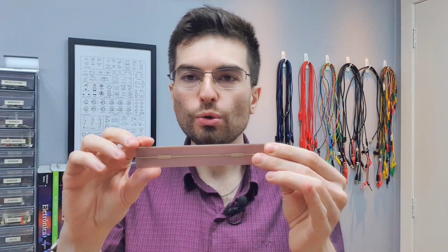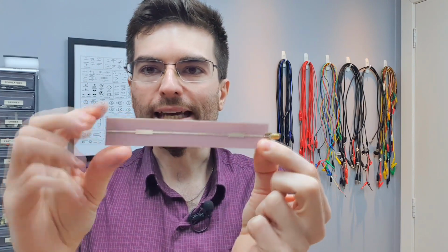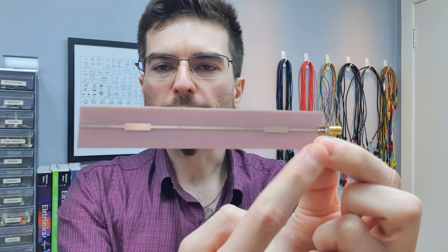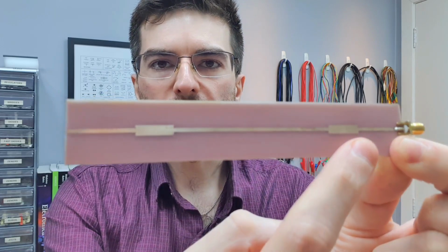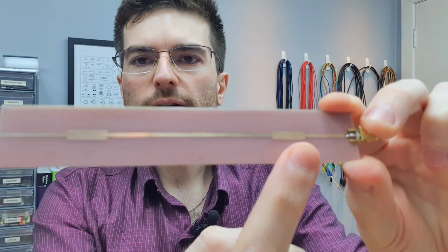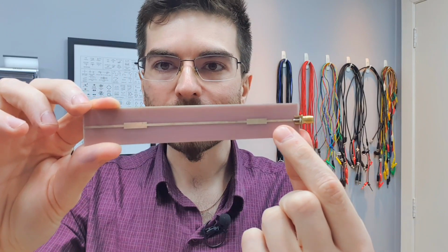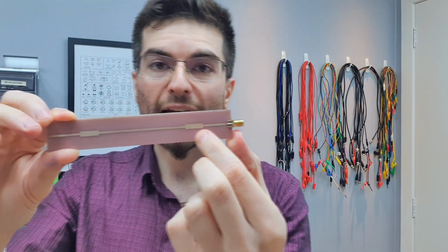So what we are going to do is generate a very fast pulse that will propagate in this microstrip geometry here. And this microstrip geometry is very special because it has a 50 ohm transmission line, the narrower trace, and also two impedance discontinuities. One discontinuity here and another one here. As the pulse propagates, and the propagation happens in time, this is why time domain methods are so interesting, it will reach one of the impedance discontinuities, and part of the energy will be reflected back.